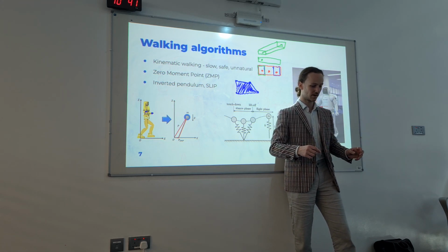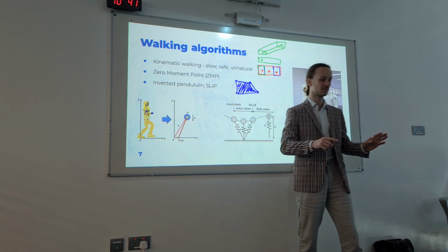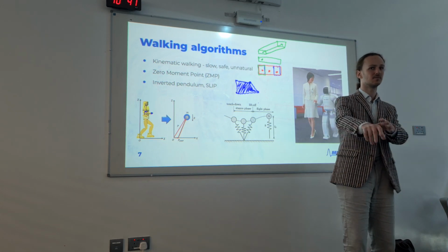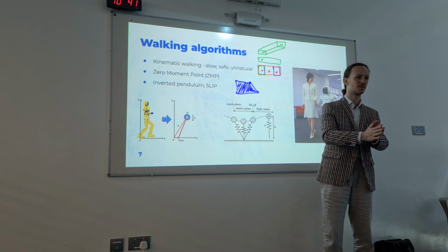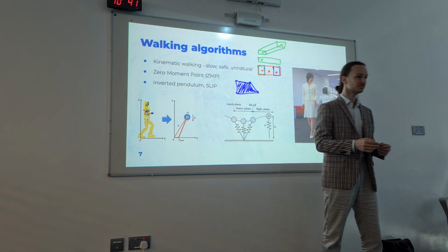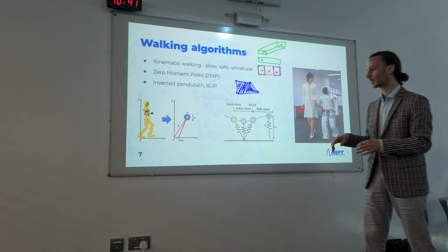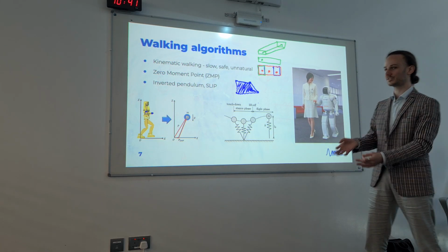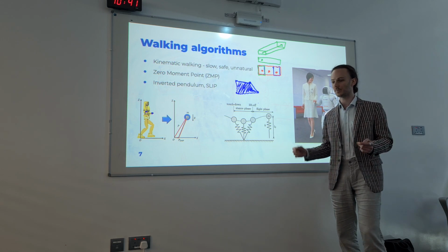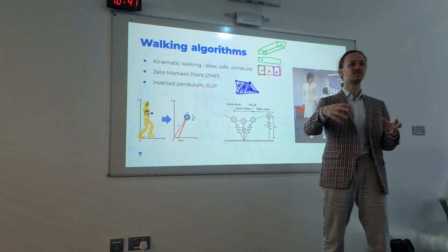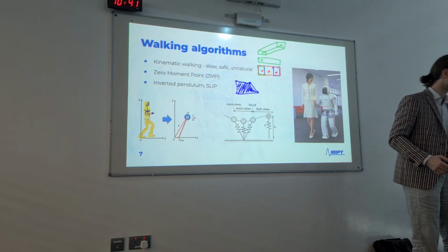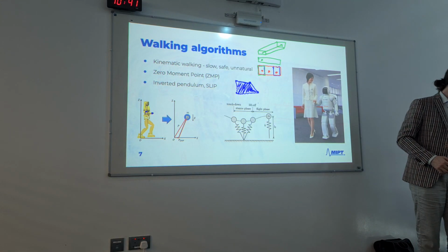Just after the stepping of the leg, I have to go through a certain trajectory, and then the same will be repeated, but in the mirrored mode. So if I'm walking straight, I have to go along a desired trajectory. That's it, as an inverted pendulum. And the rest, the exact stiffnesses, the exact forces, will be added on top of this model.